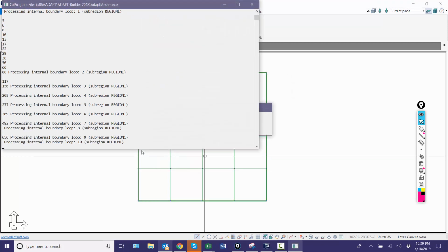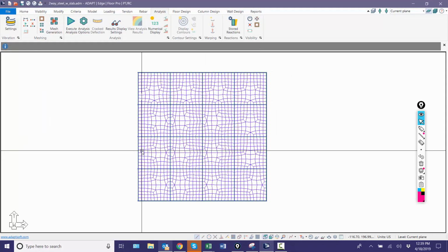And similar to concrete beams, the program uses the properties associated with the generic material and its particular material designation. And this gets entered into the global stiffness for the structure. So we will have interaction between the concrete slab and this generic element, similar to interaction between, let's say, a concrete slab and a concrete beam. They're handled in the same in general terms with just different properties, both material-wise and geometrically.